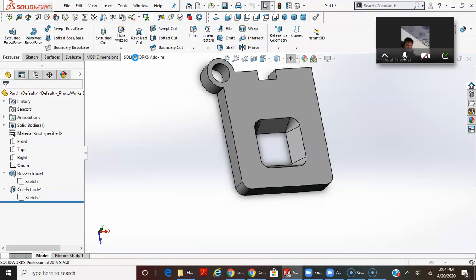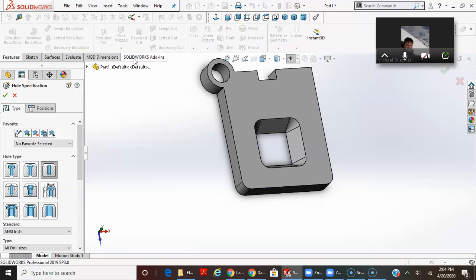and then it shows a counterbore symbol, and it shows a diameter 140 through. The counterbore diameter is 250 thousandths with a depth of 200 thousandths deep. So I'm going to select, I think it's selected now, the counterbore hole,